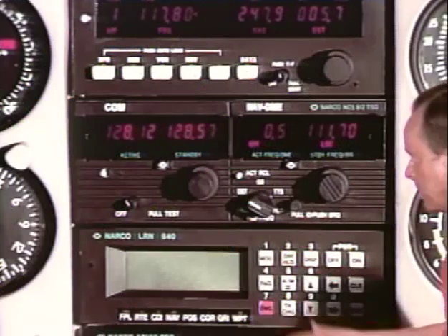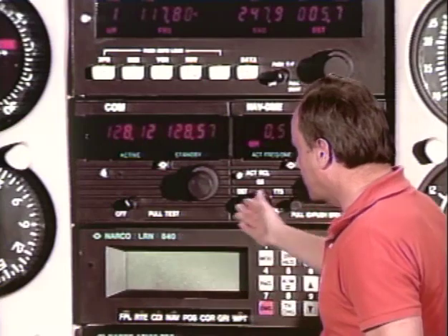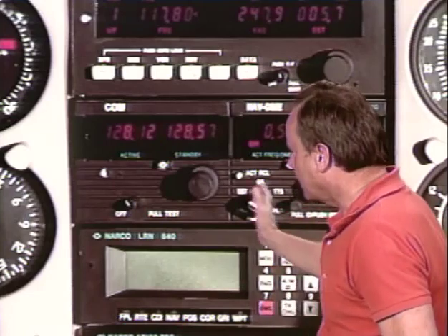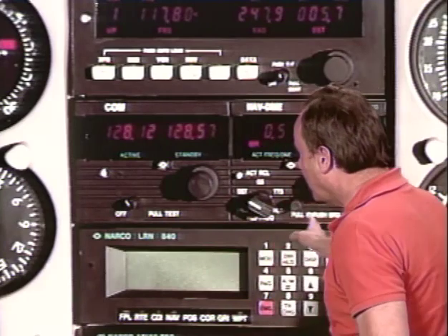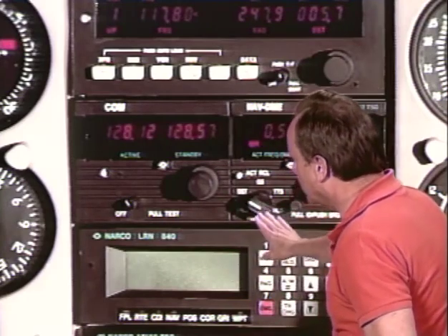Now let's assume as a mechanic you install radios or avionics in an aircraft and the associated antenna systems, and let's assume you install them forward of the CG limit. Now the question is, is this going to affect the empty weight and the useful load of the aircraft? And the answer is yes. Anytime you install some new equipment in an aircraft, including avionics and antennas, it does affect the empty weight and useful load of the aircraft, and you would have to recompute the weight and balance of the aircraft.